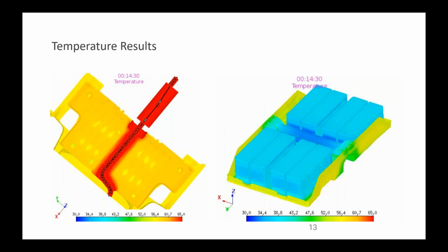So there are different considerations here, and they're actually design trade-offs where adding more protection might insulate the pack more and cause a higher temperature inside the pack, but then you can maintain your cooling strategy to limit the temperature of the cells.